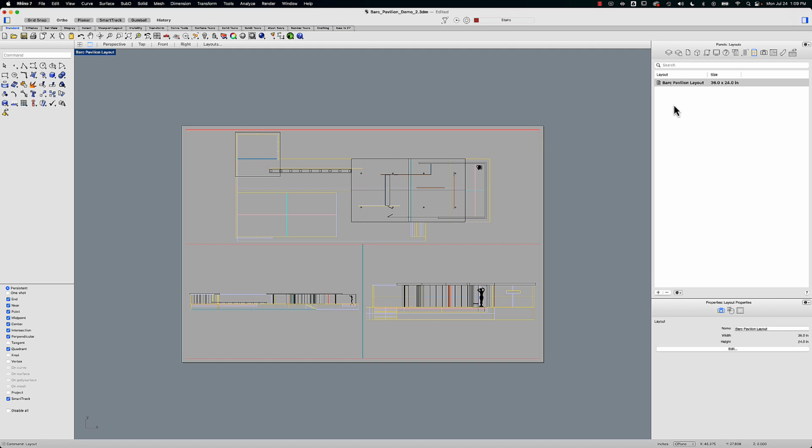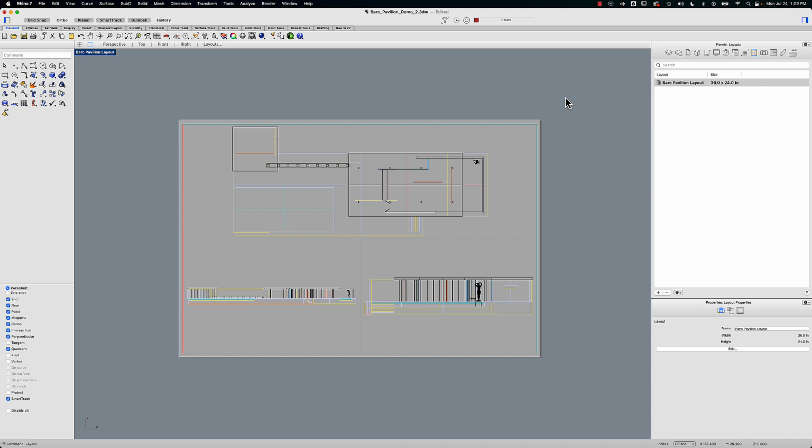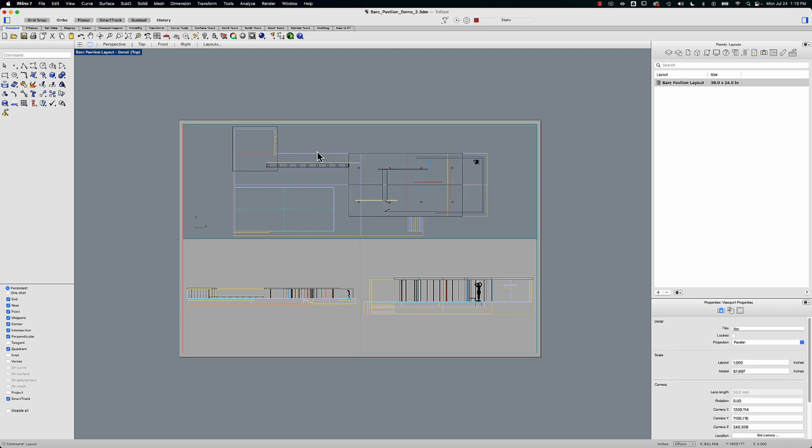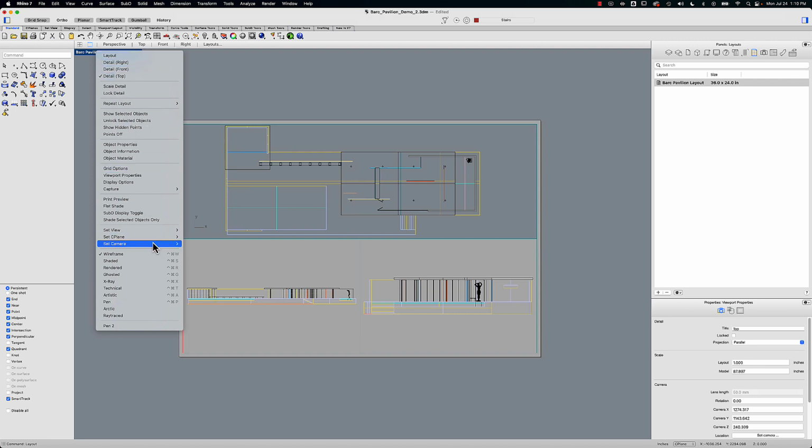And we can save multiple layouts, so just starting with this one now, and it's going to tell us what size it is. So what's really happening here is it's extracting views from different viewports, right? If I go into this top panel and double click, you'll see that I'm actually going into the top view. And I can use my hotkeys and navigate around just like I would normally in the Rhino file. But what I actually want to do is change this to perspective view. So I'm simply going to right click here and set my view to perspective.